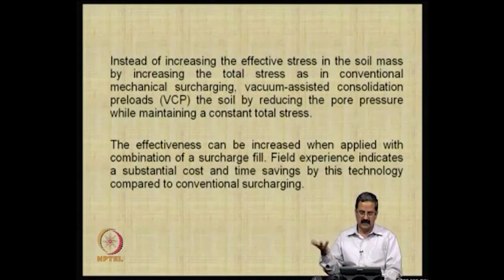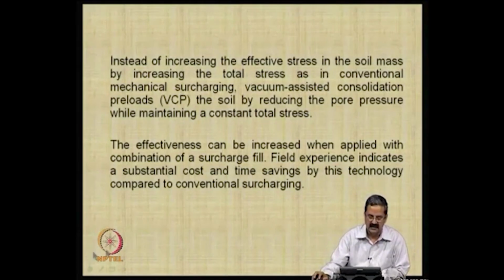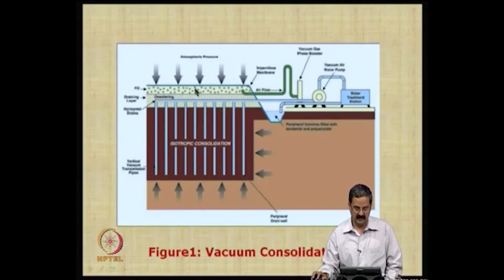As you start removing water, the effective stress increases. The effective stress can be increased further when applied in combination with surcharge fill. Field experience indicates substantial cost and time savings with this technology compared to conventional surcharging. Of course, these are mostly in places outside. Here is an example: this is the area to be consolidated, and these are the sand drains.